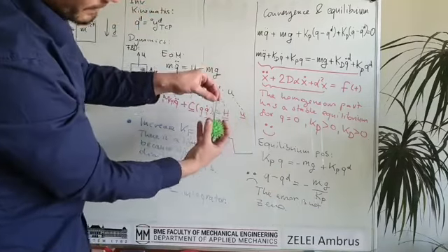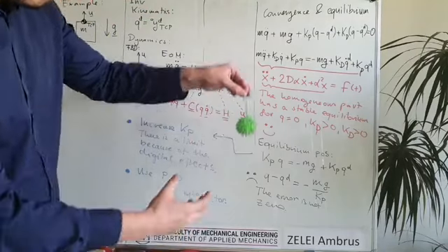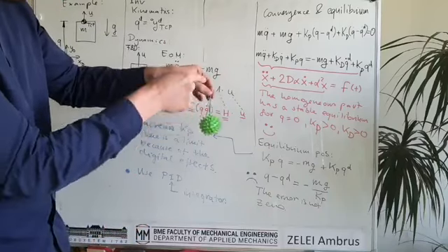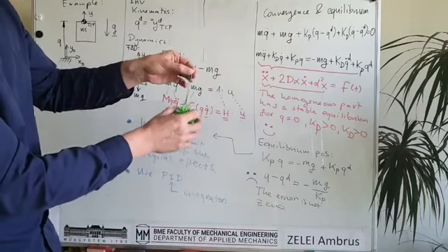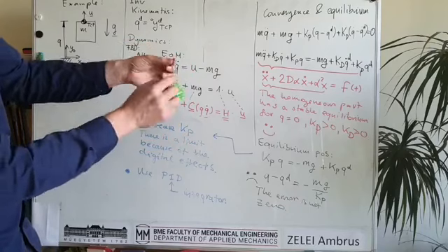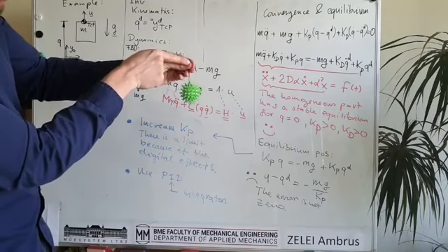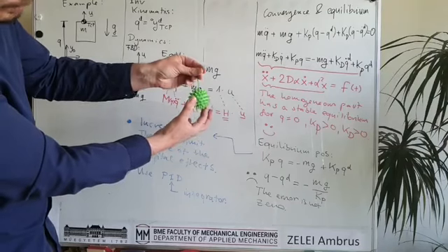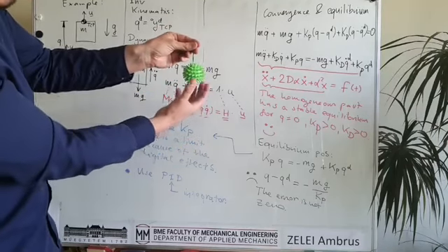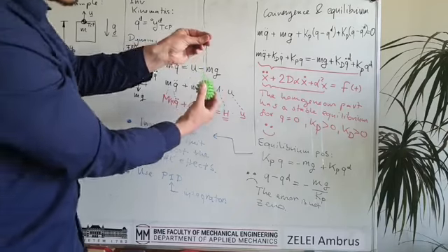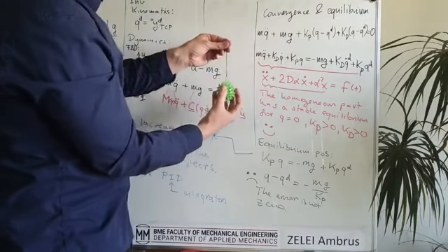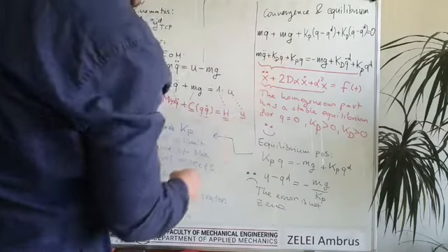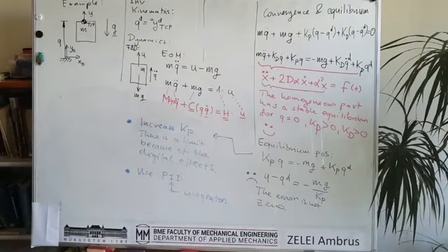Or if the desired position is accelerating, there is also some elongation of the spring and damper system. Now the desired position is my finger, and the real position is the position of the ball, and depending on the external forces, this system can have different elongations. That's the problem if we simply use a PD controller.